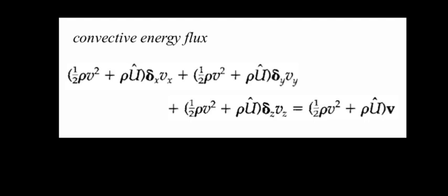Now we have the total energy flux vector, which includes terms like τxx into Vx plus τyx into Vy plus τzx into Vz, which is the rate of work done per unit area due to viscous stresses. When we consider the combined energy flux vector, its x component Ex can be expressed more fully as Ex equals ρ(E plus half V squared) plus P into Vx plus τxx into Vx plus τyx into Vy plus τzx into Vz plus Qx. Similarly, Ey and Ez would have analogous forms involving Vy and Vz, the corresponding shear stress components, and Qy, Qz.